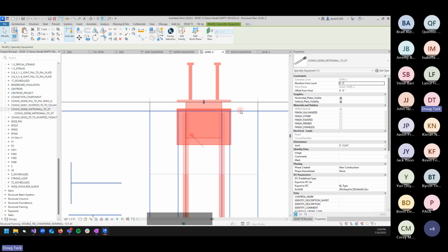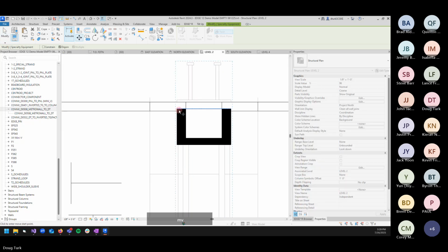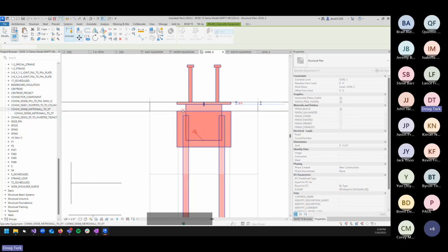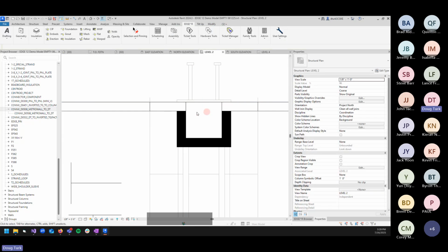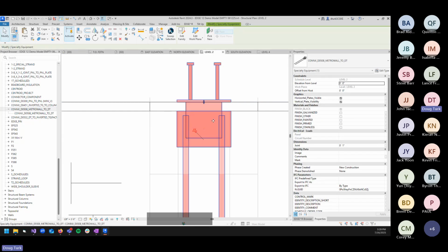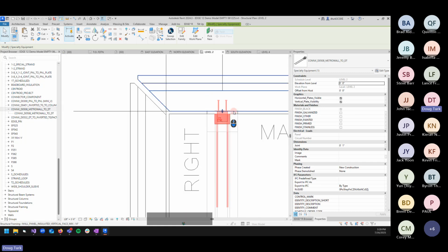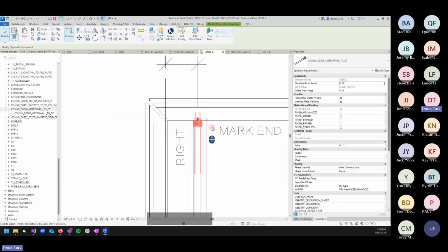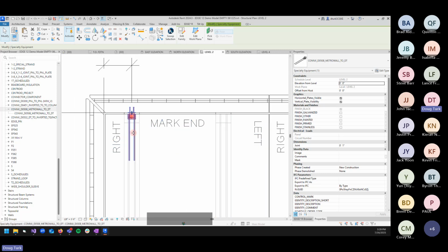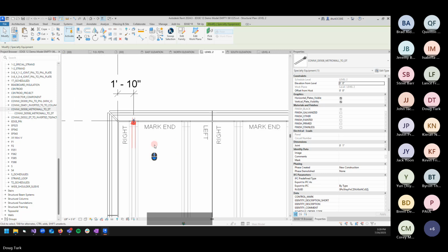Now, what you may want to do here, if you find that this isn't aligned like it is here, we can go ahead and do that and then grip handle it back, and that quickly resolves the joint. Another thing to note is that this is actually built as a nested family, so the plate in the wall will be treated as an independent element of the plate in the T for the purposes of ticketing. So you're not going to have to intentionally hide anything or remove anything. It's got intelligence built into it to know where each is supposed to go.